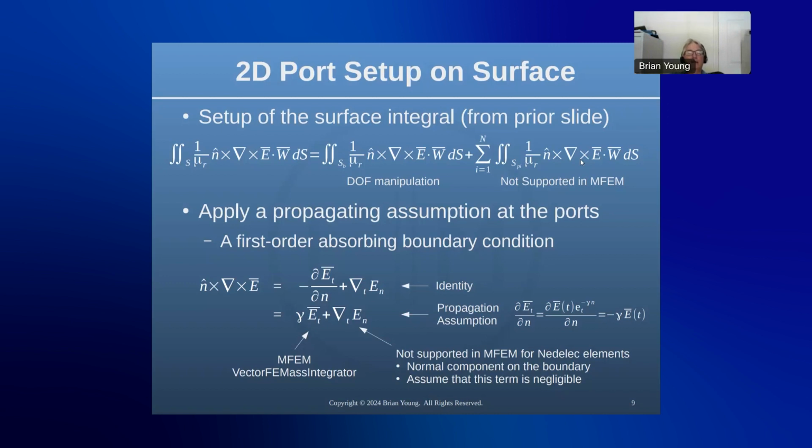So I don't know how much all that will affect practical applications. All I can really do is just start building up good examples and seeing how it goes, and then maybe I'll figure out a clever trick to get around that. But that's sort of what I'm expecting right now. But in the real world applications I'm familiar with, the even and the odd mode gammas aren't really very much different. And you're primarily interested in, say, the odd mode. So if the even mode's a little bit off, you really don't care that much, I don't think. I'll find out when I start working my way through those.